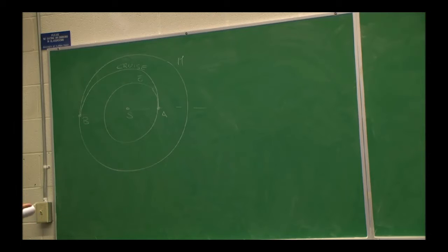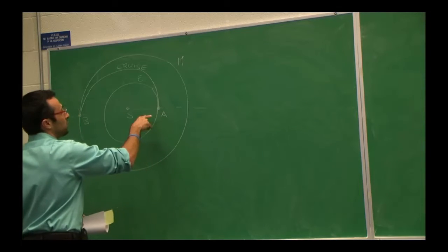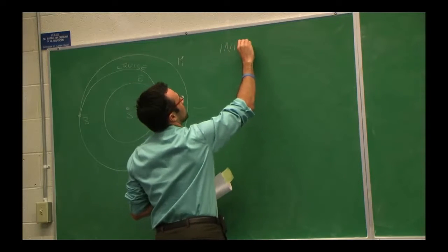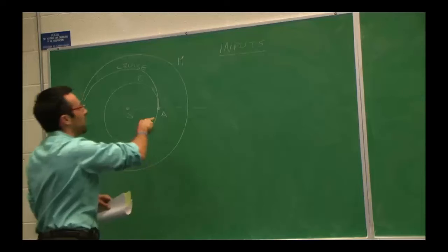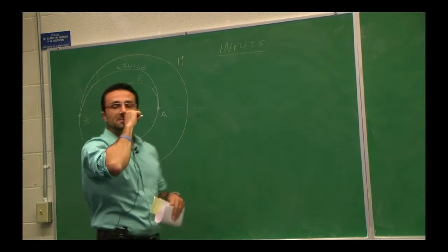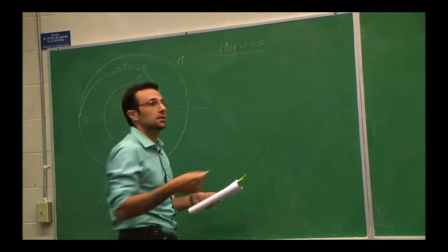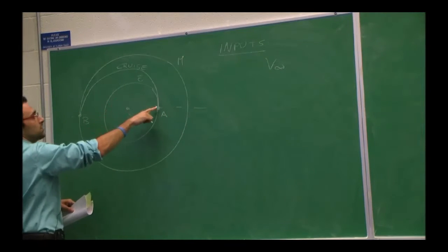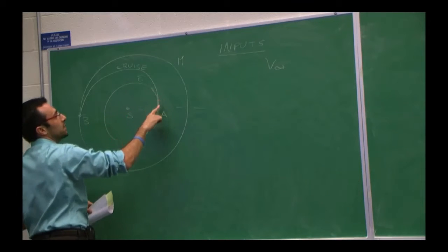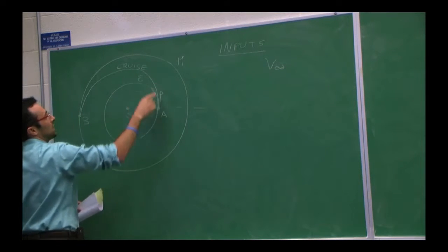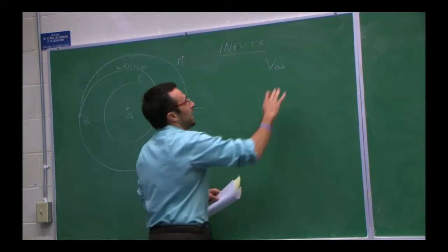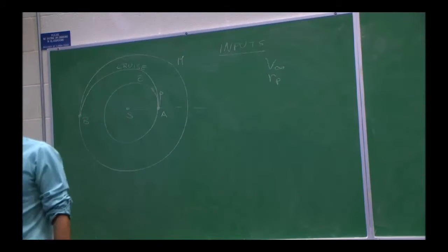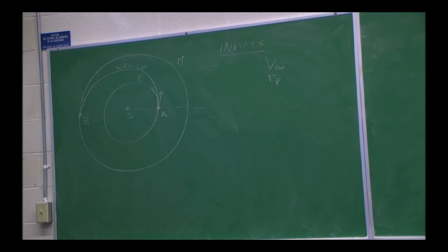Let's just refresh what we did there. We said, okay, I'm inside the sphere of influence, and I have a few known things. So the inputs for solving the problem from the departure point of view, what do we have? You have V infinity. You need to make sure that you're adding enough velocity to the velocity of the Earth so that you can leave the sphere of influence and have the correct heliocentric speed to be on the cruise trajectory. And probably you had some initial parking orbit. We just assume that we are at some circular orbit of radius rp. That's a reasonable assumption.